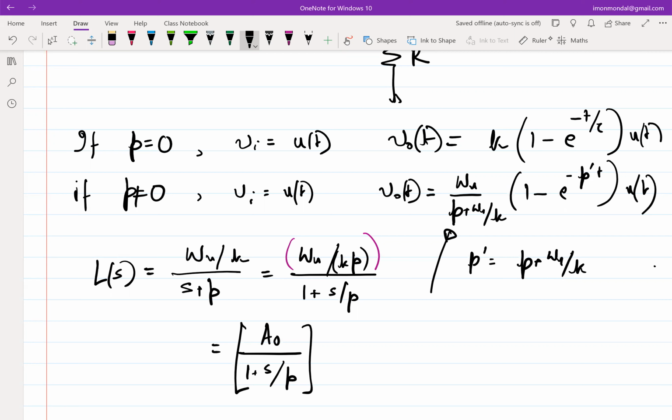And that UGB, whatever it may be, we'll call it omega U loop. In this particular test example, it happens to be omega U over K. This is important because this is a test case that we are running with. After some time, you will see that we'll replace this test case with a generic system where you can have multiple transistors. You might not even have a resistor divider. But if I plot the loop gain, you will get some frequency where the loop gain cuts the 0 dB line. And that becomes a very important set point for your analysis.